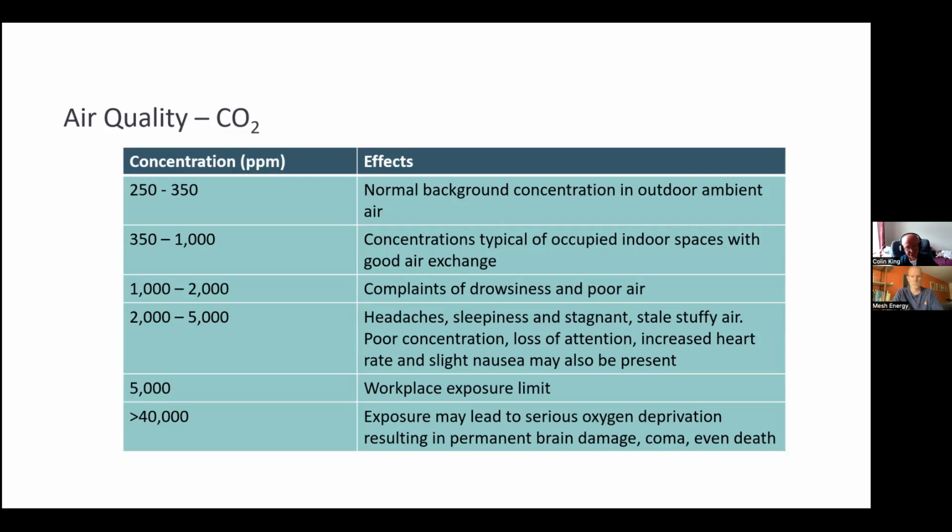If you go into a meeting in an old building and measure the parts per million of CO2, you'll find it's not uncommon in small meeting rooms for that to be up around the 4,000 mark, which is why people find it difficult to concentrate in those meetings. And even in some of the older schools, air quality is a real issue, and something Ireland's doing a lot of great work on, bringing in standards for indoor air quality in Irish schools, which we've yet to embrace. And then you've got 5,000, which is actually the legal limit for workplace exposure.